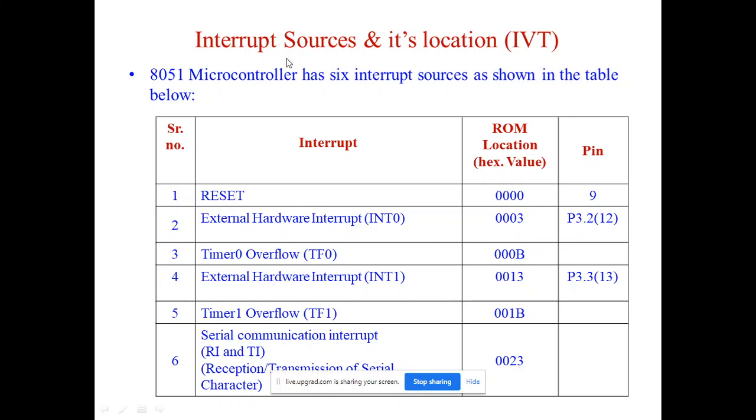In this fashion, when any interrupt arises, the controller jumps to the respective location and takes the starting address of the ISR. From that starting address it will start executing, one by one, all the instructions of the ISR, that is the interrupt service routine, to serve that interrupt. After completion, the last instruction is RETI, meaning return from interrupt, and then it goes back to the main program. All of you agree with this concept?